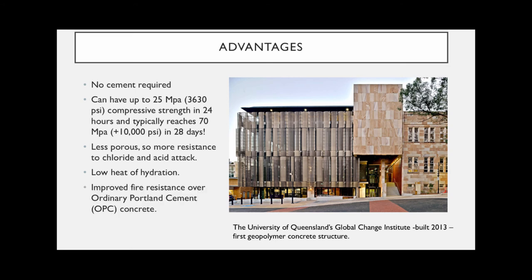We already said it has low heat of hydration. One of the things that is interesting is we think of concrete as being fire resistant, and it is. It's not flammable, it has resistance at some point, but it will fail in fire, and it tends to be a little bit of a catastrophic failure, and the geopolymer has a greater resistance to that than regular ordinary Portland cement concrete. So that's your brief introduction to geopolymer. There's still research that needs to be done, but it's an exciting product, and I encourage those of you interested to take some time and look a little deeper into it.